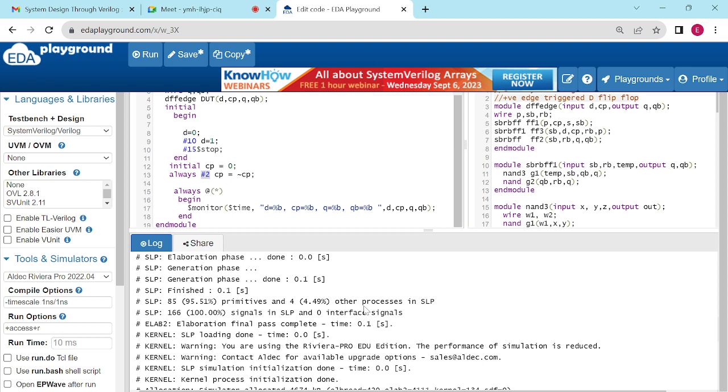Say we are trying to design a MAC unit, then Verilog is sufficient. We can write the code and simulate it in EDA Playground, an open source online platform, and for synthesis you can use Cadence Genus or similar tools. Then further you can have the steps.